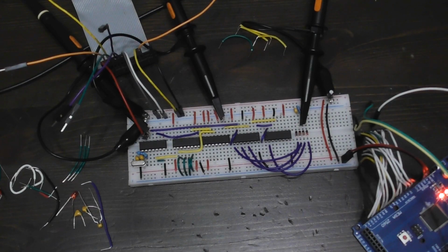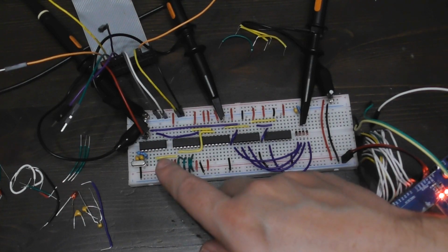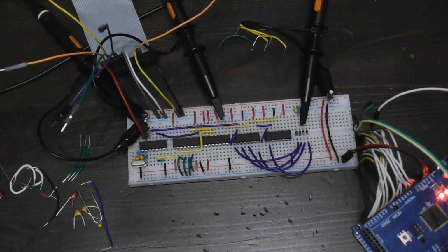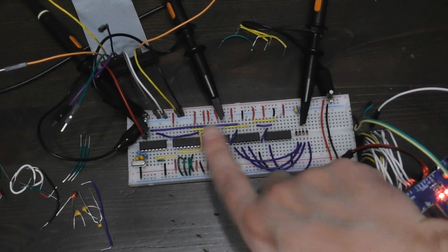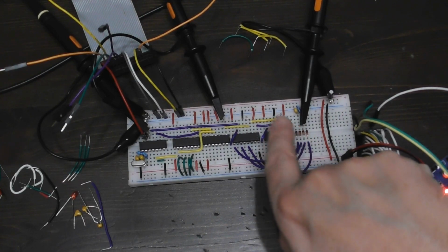So I've tried out a couple of ways now to delay my clock slightly so that it doesn't rise too quickly after the data line changes state from the floppy disk drive. Now, the first thing I did, because I didn't want to completely redo the whole circuit, was just chain more of the inverters together to try and get a bit of delay from that. That didn't seem to be sufficient, so I bit the bullet and I have actually rearranged the circuit a bit. I've tidied a few things up, as you can see, clipped some diode leads and so on so they're nice and short.